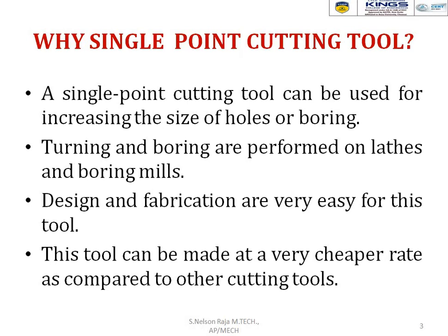And why a single point cutting tool? What is the necessity of a single point cutting tool? A single point cutting tool can be used for increasing the size of holes, or boring. Turning and boring are performed on lathes and boring mills. Design and fabrication are very easy for this tool, and this tool can be made at a very cheap rate compared to the other cutting tools. So these are the major necessities of a single point cutting tool.